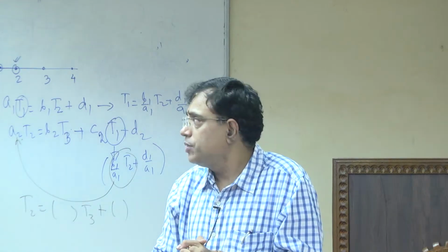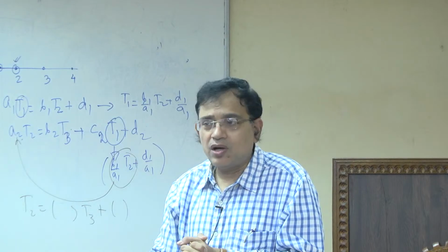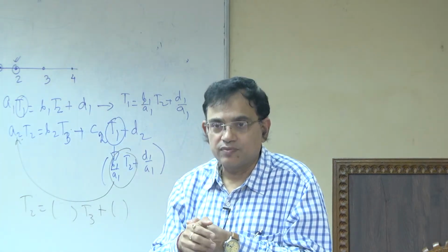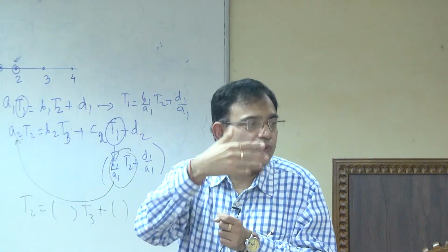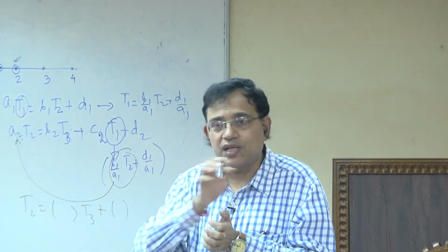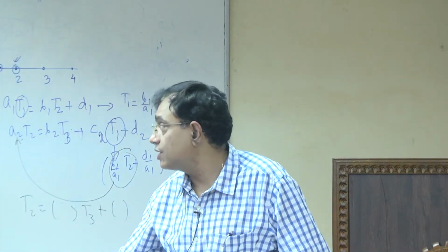Sometimes people prefer an implicit scheme. Why? Because before standardizing a CFD problem you have to make a lot of trials. To make the trial you can keep a coarse time step and see that at least it is giving physically the correct thing, but with the explicit scheme you cannot keep a coarse time step, because that can give you wrong results.